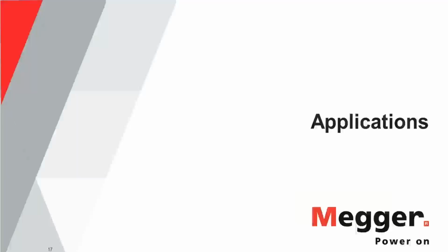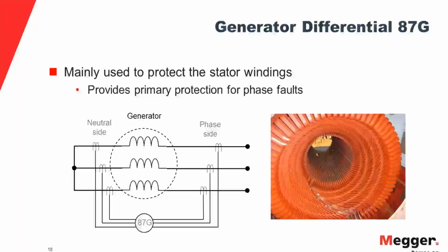So what you do is you put a variable resistor, which is called a varistor, right across the relay circuit or the relay input, which prevents any damage to the relay from high voltage levels. Now, in this protection method, the CTs are connected in parallel with each other. And typically, all the CTs will have the same ratio, and they are used at the full tap of the CT.